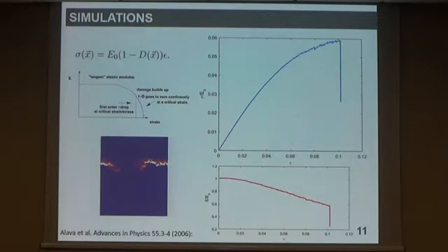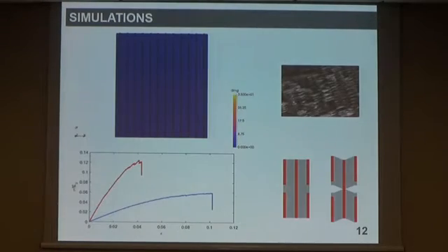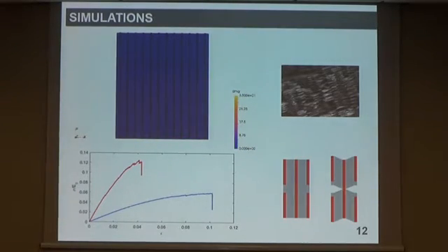So the idea is then to add some structure inside, here some stiffeners, so some line inclusions which were 100 times stiffer and 100 times less tough. If you do the same test, you will see that damage accumulates near the tips of the reinforcement and then propagates the crack.